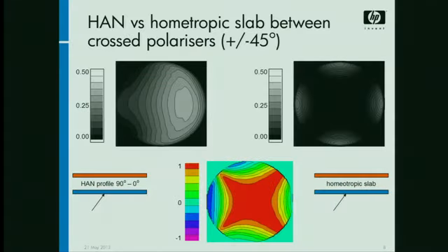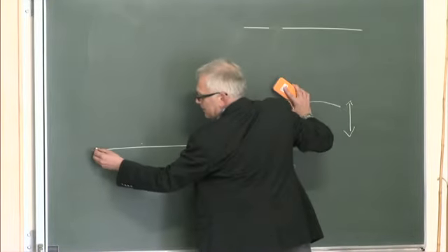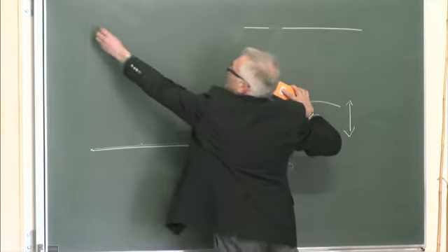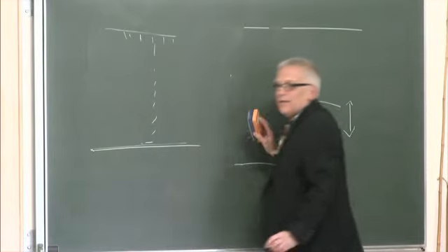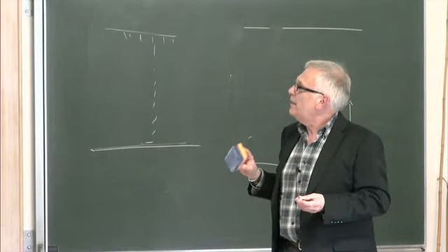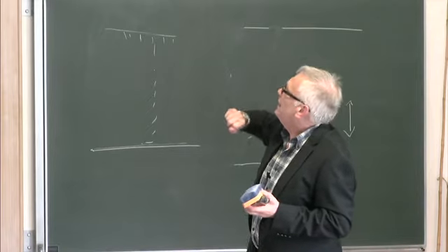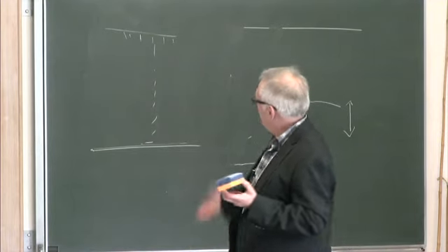Optimization, well, we can calculate the optics as light passes through the cell, and this is just a simple hybrid cell. I guess most of you probably know what a hybrid cell is, but on one surface we've got more or less planar alignment, perhaps a slight pre-tilt, but in some general uniform direction, and on the top surface we've got homeotropic anchoring, and the liquid crystal is obviously bending and splaying to match those boundary conditions. So that's just a simple cell, but we could do some optics calculations. On the right then we've got the dark state, if the liquid crystal is all homeotropic. On the right hand side we've got the sort of optics you get if you just have a hybrid cell.